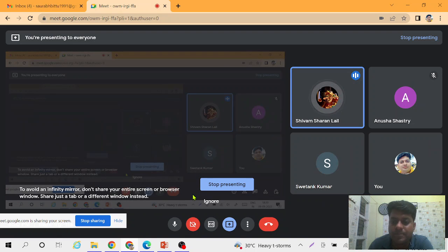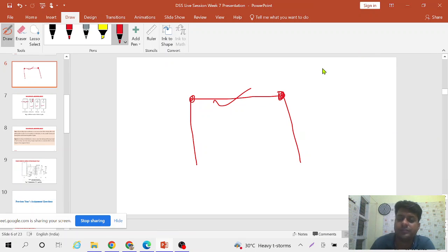Yes, sir. To prevent a brittle failure and have a ductile failure, we go for the under reinforced section, and in over reinforced section, it is not a ductile failure. The concrete is brittle; it just breaks out in compression. So that's why over reinforced section is undesirable. Yes, what happens in over reinforced section, we don't get any alarm before failure.